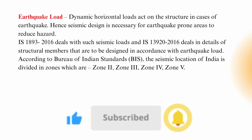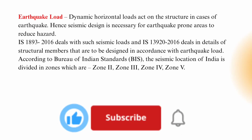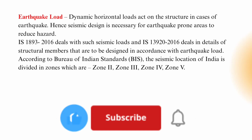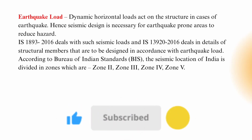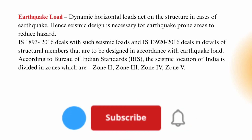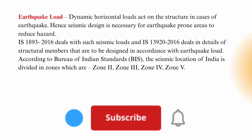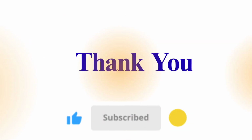So all these loads have a different impact on the buildings. Different areas have different weather conditions, which in turn have an impact on the variety of loadings. Some areas may experience combinations of loading like dead load plus live load plus earthquake load, or we can say dead load plus live load plus wind load, and many combinations are there.